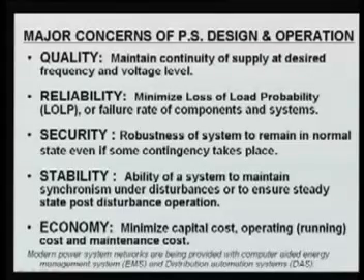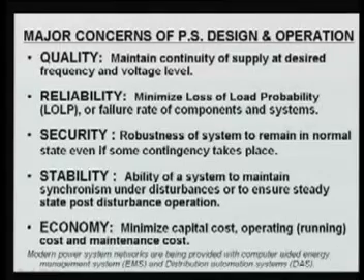The fourth concern for power system design and operation is stability. As you know, stability is one of the big concerns in an AC power system. It is the ability of a system to remain in synchronism under disturbance, or to ensure steady state post-disturbance operation. This means we have to operate our power system in a secure, reliable, and also stable manner.